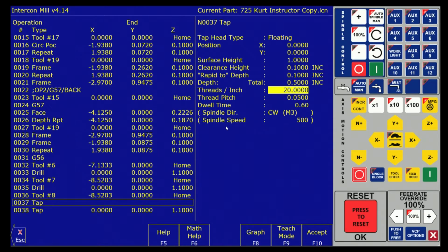So if it can't be longer, typically there'll be some note saying so. If you're in a thin part, I've machined thin parts before, you can only have so many threads, or it's poking through the back of the part. So, gosh, they had a fancy name for it. Breakthrough, I think they called it. Okay, in this case, drop my pencil. I'm going to 0 this.